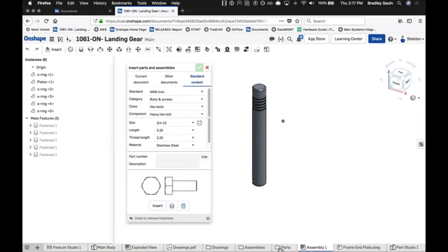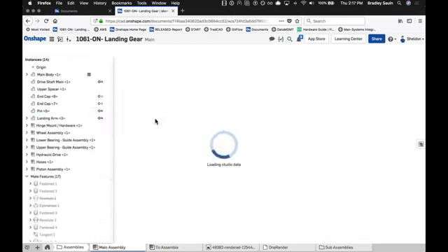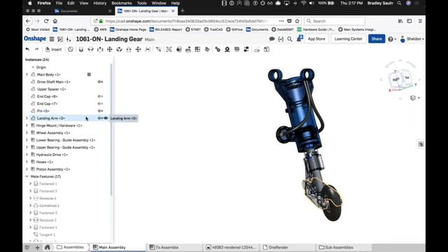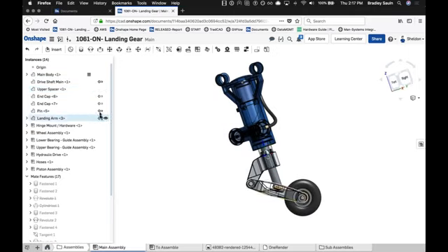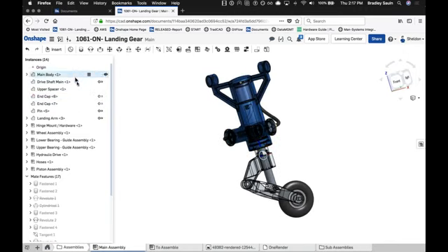If we do go to the top level assembly of this model, we'll notice that a few of these parts have been designed in context. So if we look at my instance tree on the left here, we'll see a bunch of arrows next to parts that were used as in-context references. So those are the solid arrows. And then other parts that were affected by the in-context work. So not necessarily the exact reference point, but were part of that, maybe influenced from a design intent perspective. So if I look at this drive shaft, this main drive shaft here, this was used as an in-context reference.